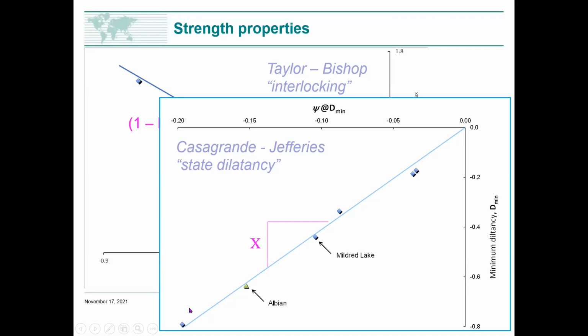And the parameter chi, I should have mentioned here, the convention is that properties in critical state models should be uppercase Greek. Obviously, lambda 10 for some reason isn't, but we try and stay with this convention of our properties uppercase Greek. So even though that looks like the letter X, in fact, it's a capital chi in Greek font. And that's the property chi. And again, it's just a slope.